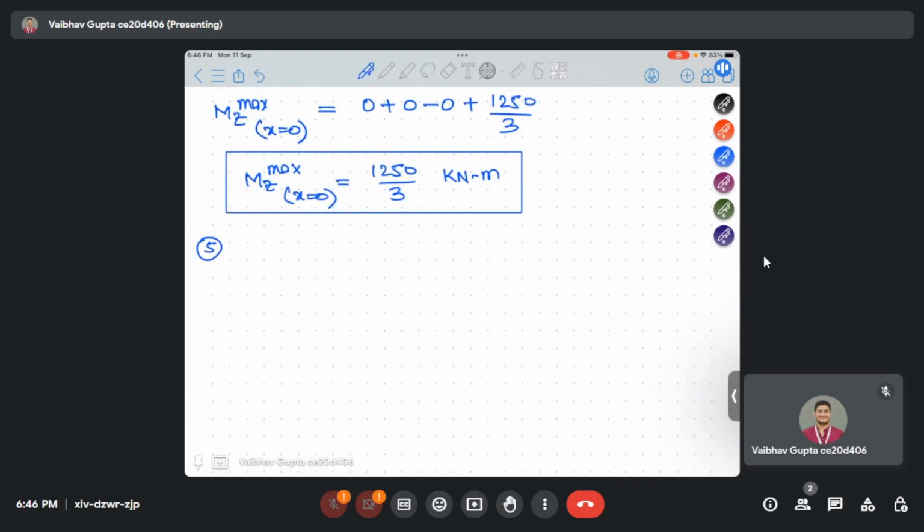So as we know from our beam bending equation, Mz by Izz is equal to minus sigma xx by (y minus y naught). Here, since it's acting at the principal plane of the cross section as mentioned in the question, y naught will be equal to 0.